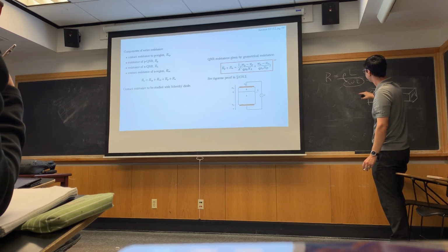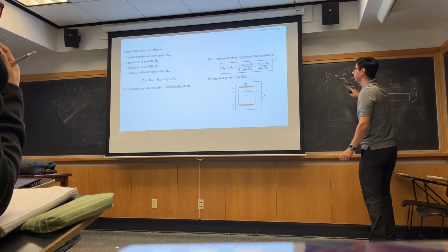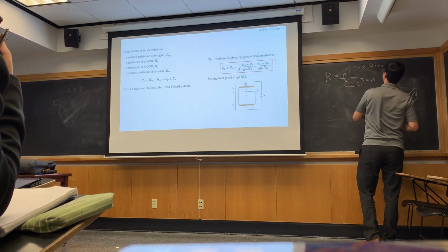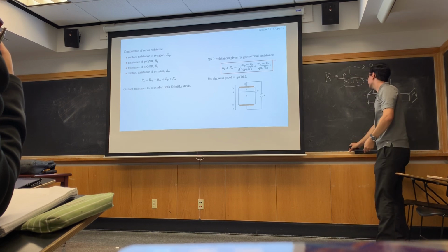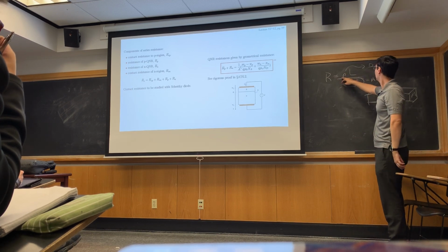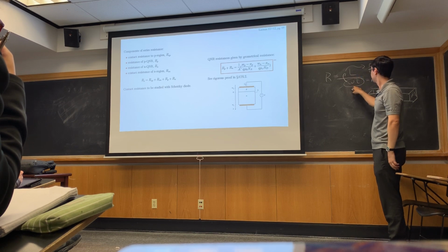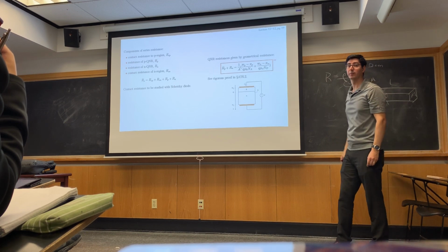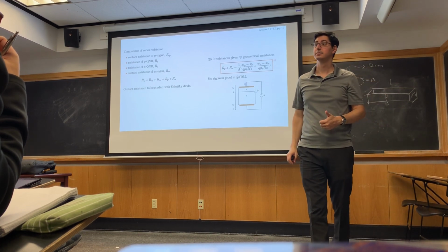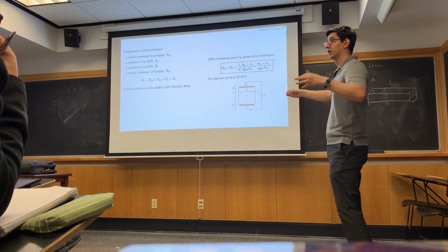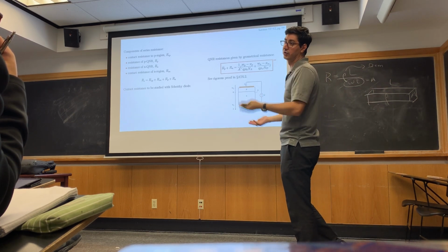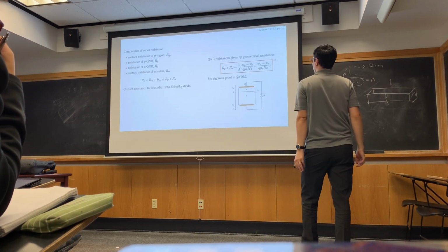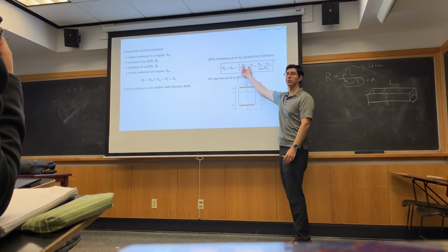And this bar has some resistivity. Resistivity is in a weird unit of ohm centimeters, or ohm distance. Why? Well, you can see when you put it all together, ohm centimeter squared divided by centimeter squared gives me ohms. Resistivity is a material property. Resistance is not. I can change the resistance of a material by just cutting it differently. Assuming it's a uniformly doped material, I don't change its resistivity. Resistivity is more general. So that's the length, WP minus XP.